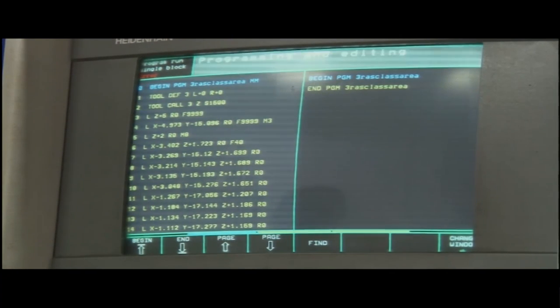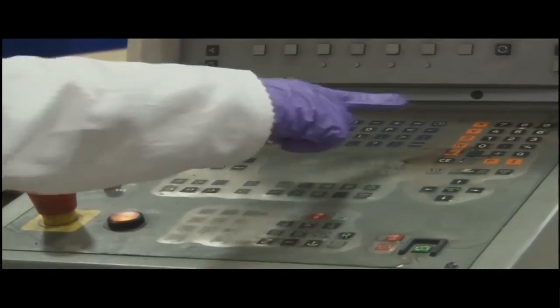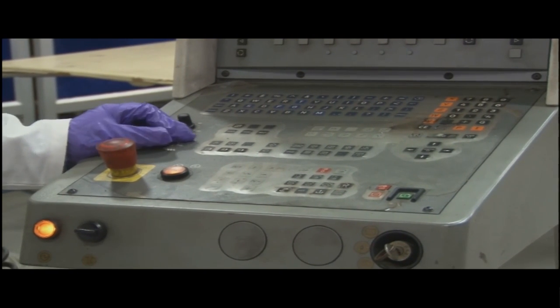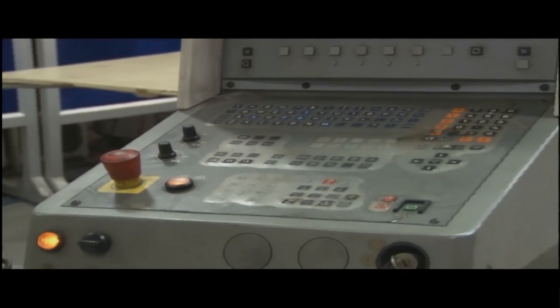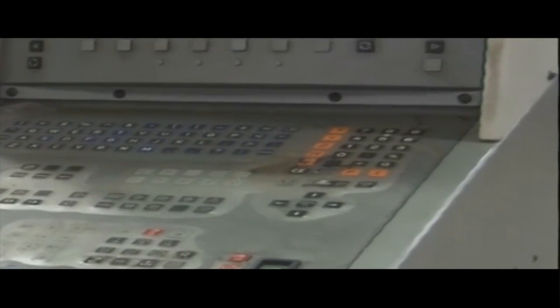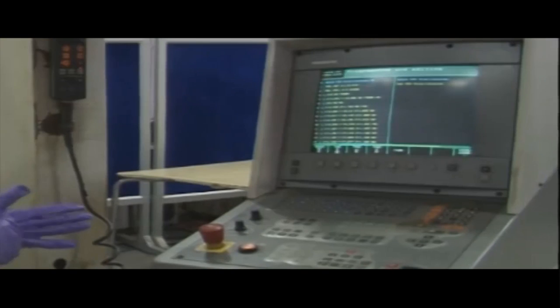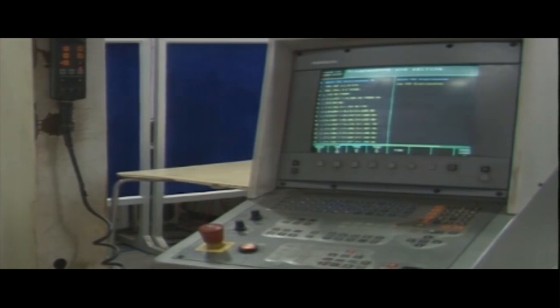We can also make small changes according to the machine setup. For that we have a control panel with the keypad and some important keys like these knobs. Feed override and feed underride can also be set. This is generally known as feed override. There is also the MDI, manual data input, button. To find the references, we can feed some small codes to see whether the machine is running properly. Small codes can be written directly on the machine.